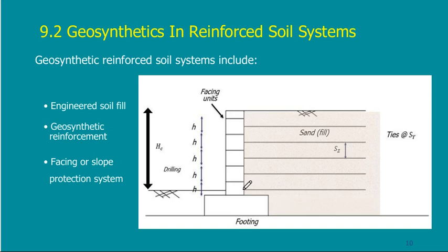Maybe for strips I can connect it at any place, but for geotextile fabric and wire mesh, it is better to put it in between the blocks. So at this level I can put my mesh, because it is as if it is a big layer of this wire mesh or fabric. And I have the fill.